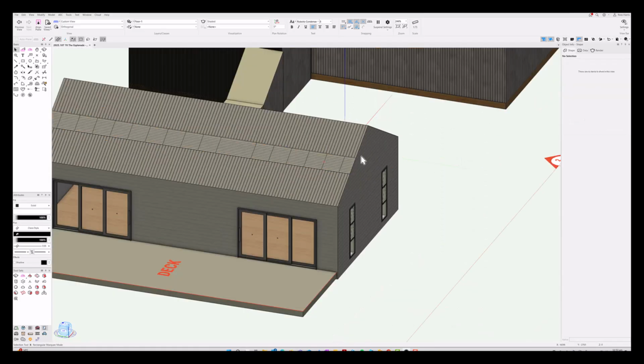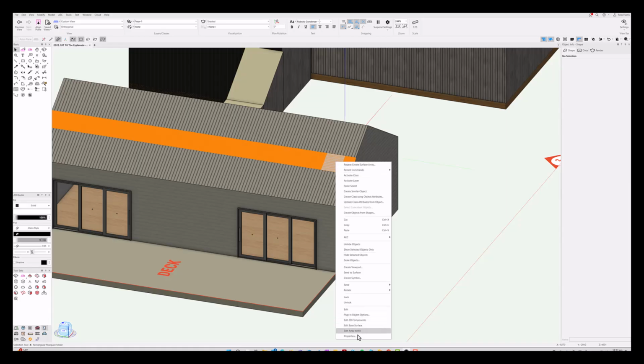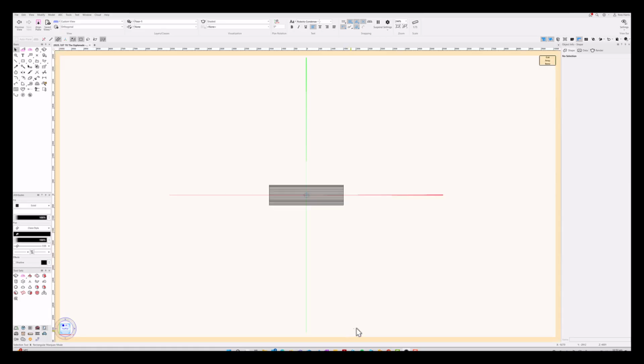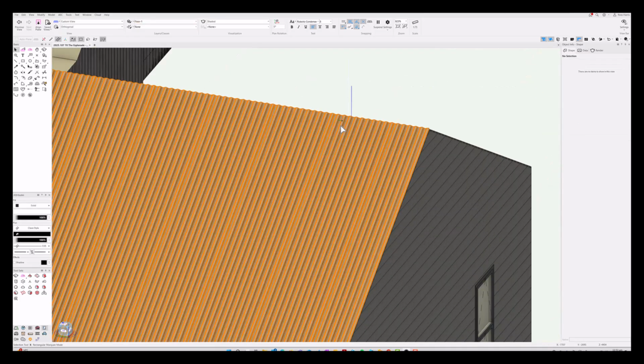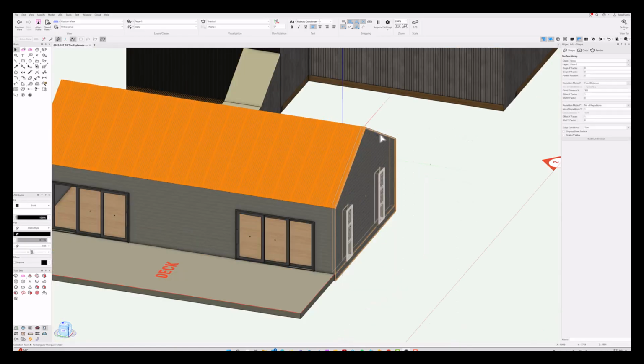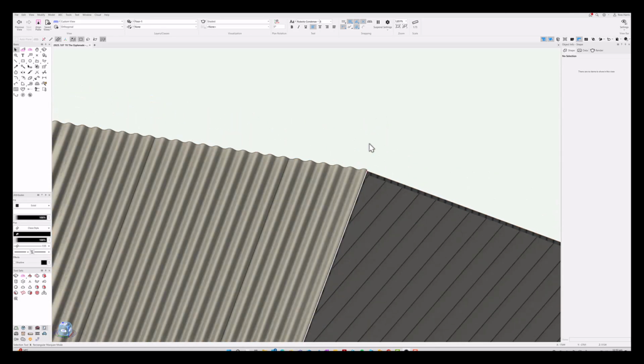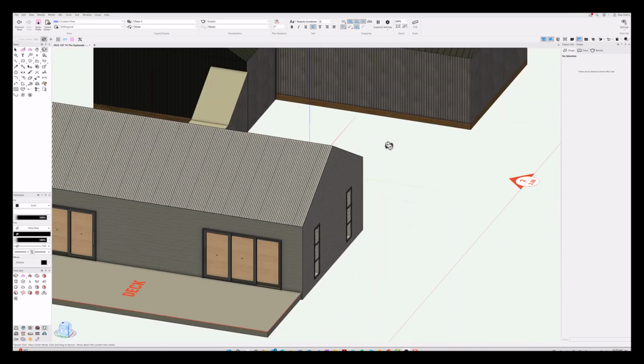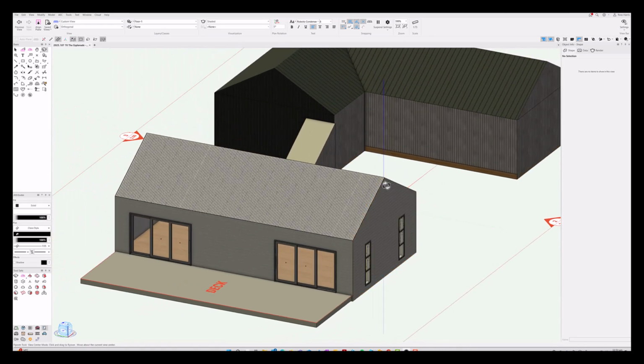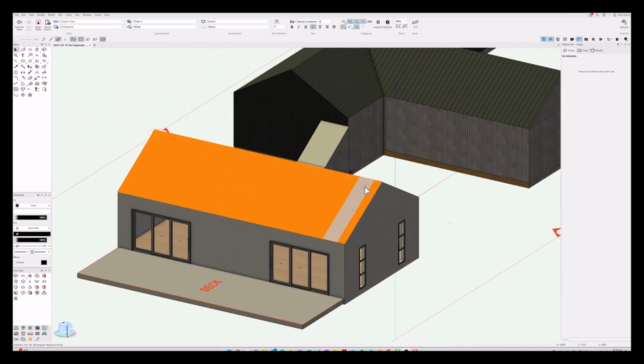Okay, problem there is our object is around the wrong way, so we right click that and go to Edit Array Items, and we just rotate that. There we go, perfect. The other thing that by default is usually left on is display base surface, which will show the polygon that creates the area to be surfaced or arrayed. So usually I just turn that one off.